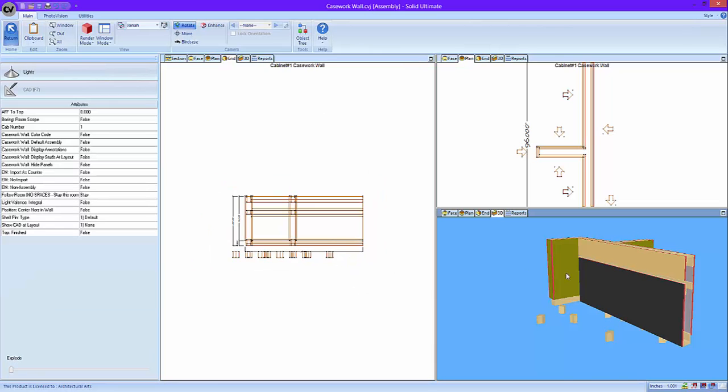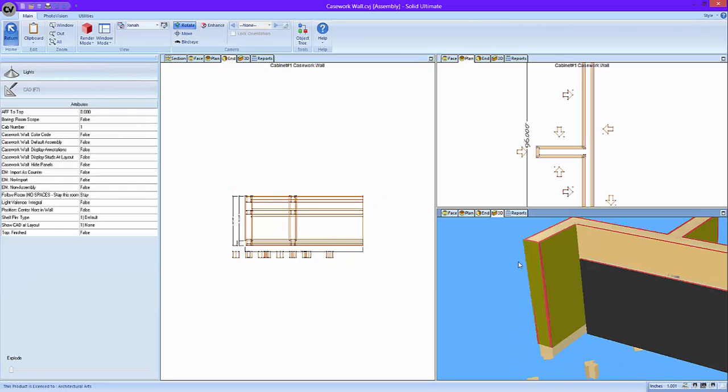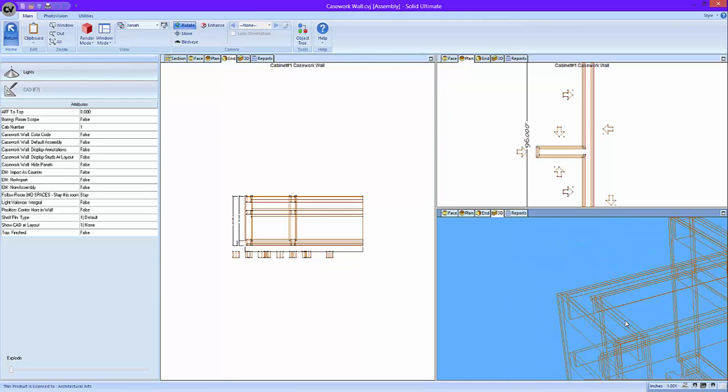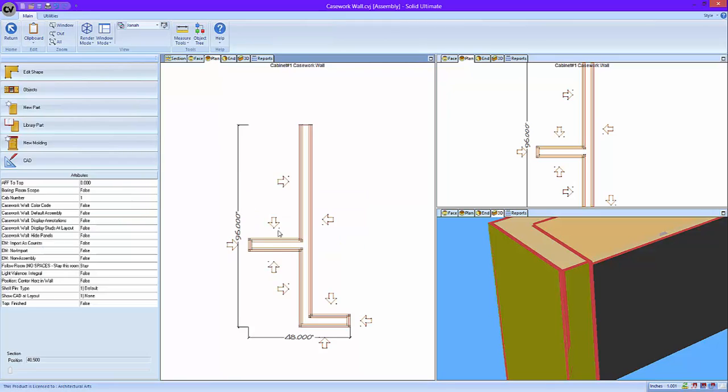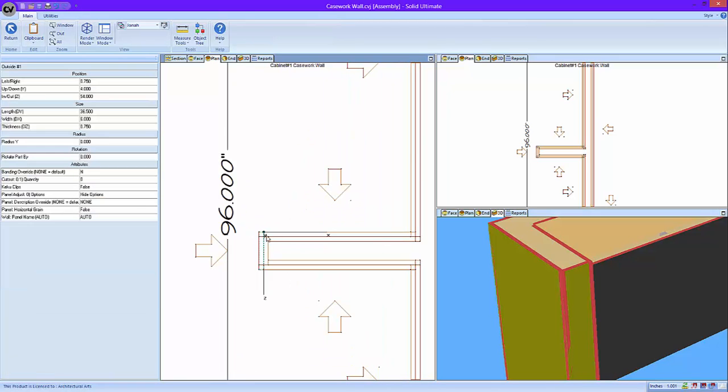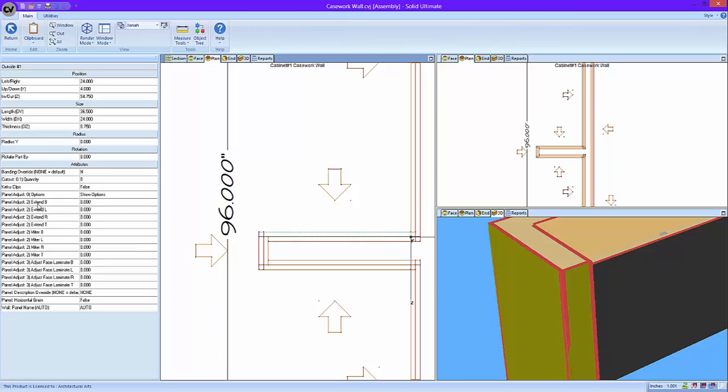Okay. You can see in 3D here we got some faces fighting one another for their Z order because they overlap. And so see what Cabinavision's doing here, just overlapping these panels. We don't want that. I have options on each panel to either extend, which just means make it bigger when we go to CNC, or miter.